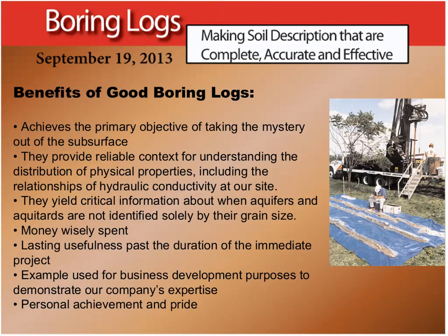Benefits of good boring logs create reliable project outcomes. They provide reliable and reproducible context for understanding the distribution of physical properties, including the important relationship of hydraulic conductivity at our site. They yield critical information about when aquifers and aquitards are not identified solely by their grain size.